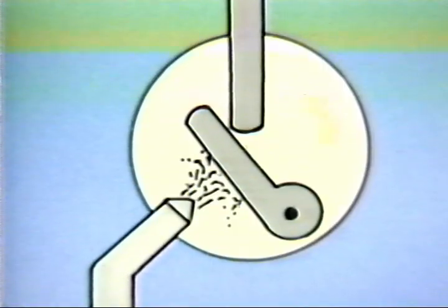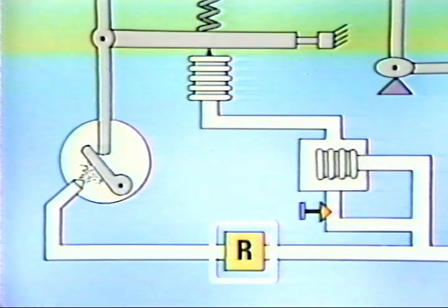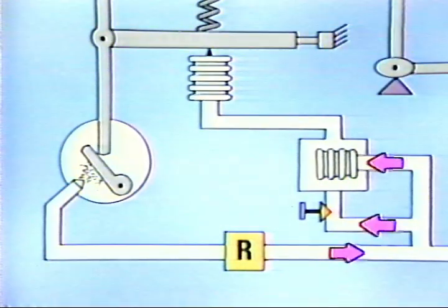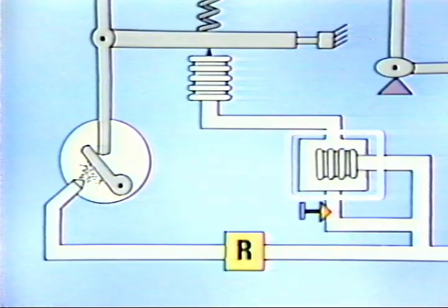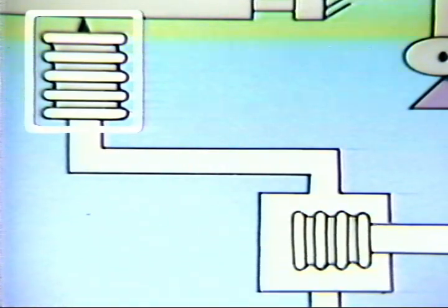When the disc is rotated, it changes the position of the flapper, which affects the amount of output that is produced by the controller. A relay converts changes in back pressure to changes in output, which are fed to a volume chamber. The volume chamber restricts the controller's output signal from being fed to the feedback bellows. If the output signal were to increase, the bellows inside the chamber would expand, restricting the output signal path to the feedback bellows. This delay would prevent the feedback bellows from balancing the movement of the input mechanism.